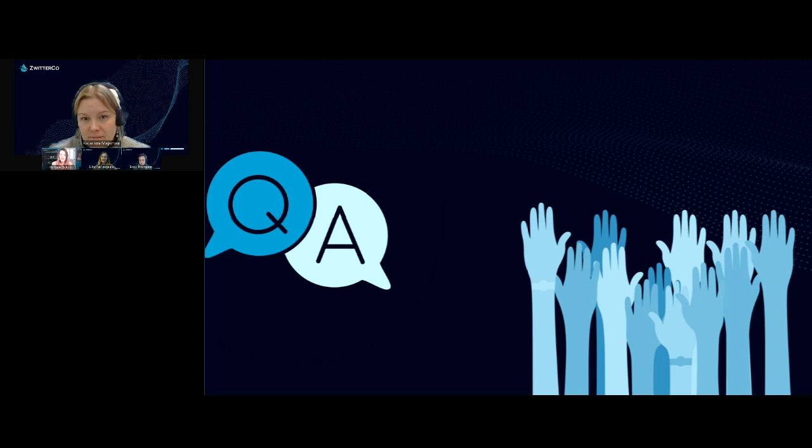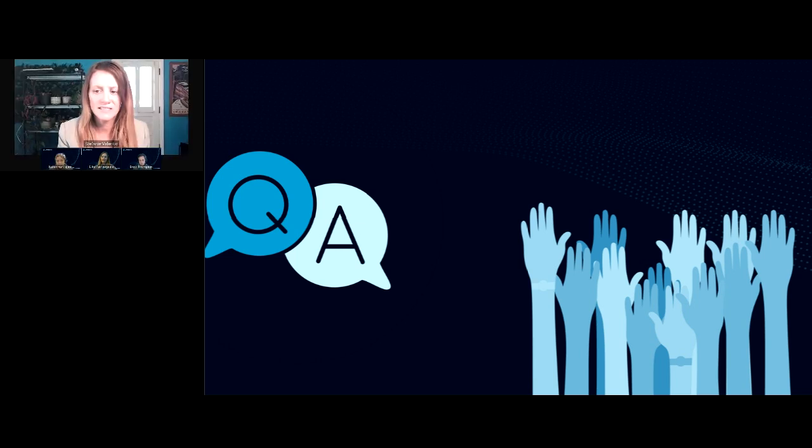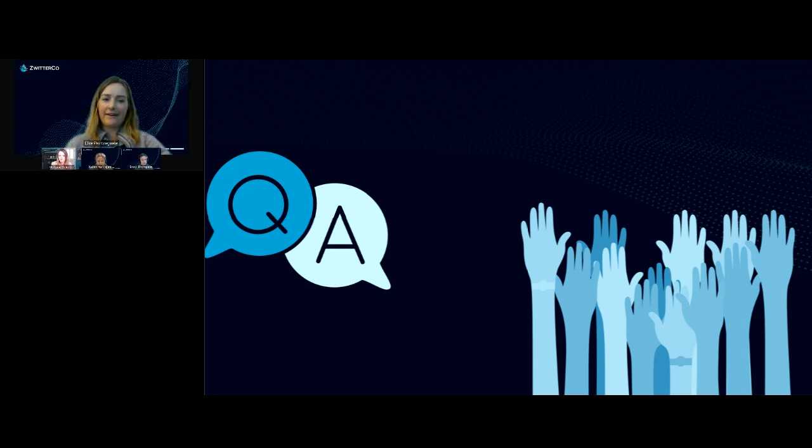Next question comes from Sam. Is there more passage of contaminants expected with the high hydrophilic nature of the membranes? So I'll chime in here again. No, I would expect very similar rejection performance compared to other RO membranes that are currently available. Just because we have this hydrophilic Zwitterionic technology, that's not going to increase passage of certain contaminants. It should be the same.